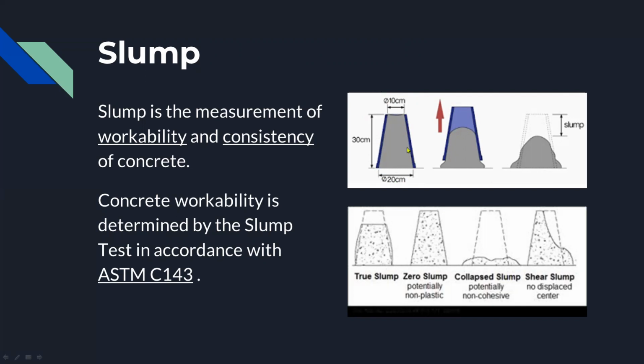Ano pang gagawin natin dito? Ilalagay natin ang concrete sample inside the slump cone apparatus, and then after processing, i-release natin ang ating slump cone apparatus. Aalisin natin ang slump cone, sample natin, and then right after, all we have to do is just to measure the depth of the slump. Ito kasi yung makakatulong natin para ma-determine natin kung ano bang klaseng konkreto ang ginagawa natin.